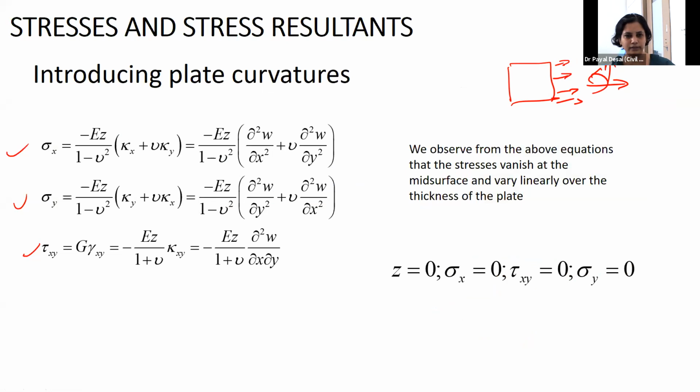In place of the strain, I am simply introducing those curvature equations here in terms of displacement W. Because ultimately my problem of plate analysis results in finding out how much is W, that is the deflection.